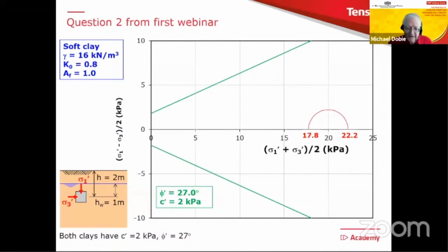So we can then calculate the effective stresses on the top and side of the sample, and that allows me to calculate that Mohr circle which you see there. The red Mohr circle comes from those 2 stresses on our specimen. And therefore we can plot the stress point, which I've done with the little black plus sign at the top. So that's the stress point defined in this stress space for the current situation in the ground.